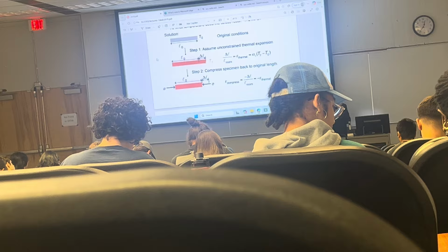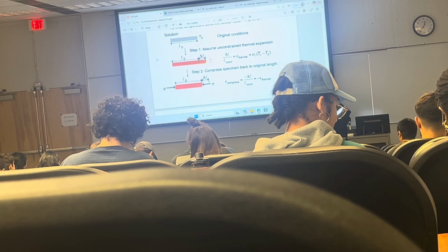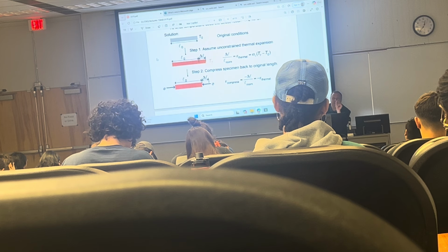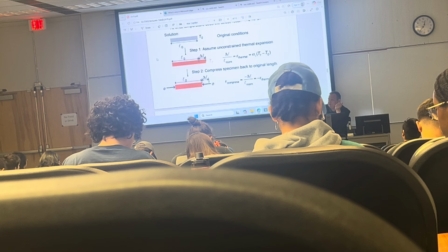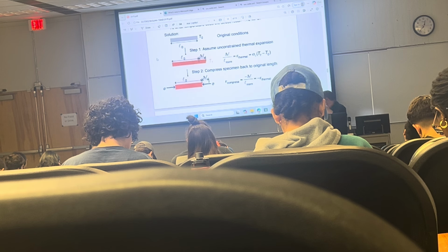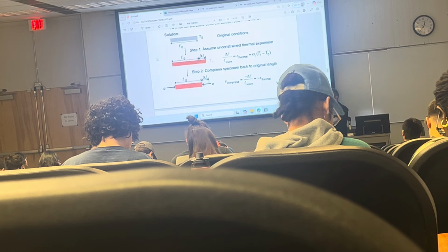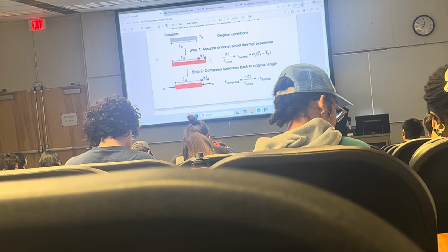Funny enough, right? They call it kinematic condition. Nothing moves. Sometimes there could be a gap. Okay, so it could be like a millimeter gap between the steel plates and whatever you're heating up. And then it would extend by that 1 millimeter and hit the wall. And once it hits the wall, it doesn't move any further. So you would account for that 1 millimeter in your analysis.